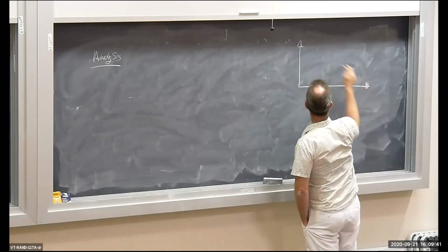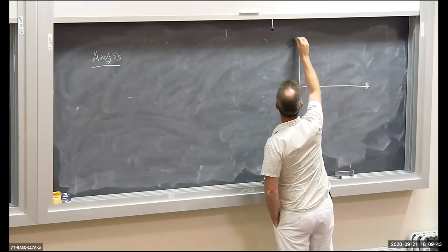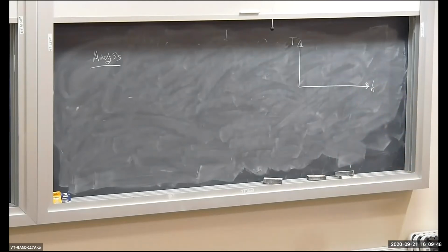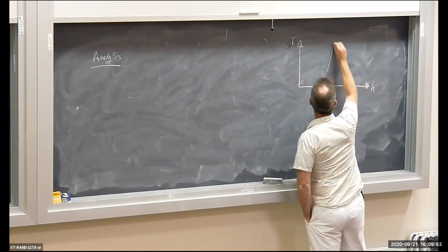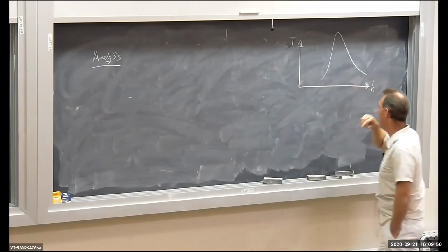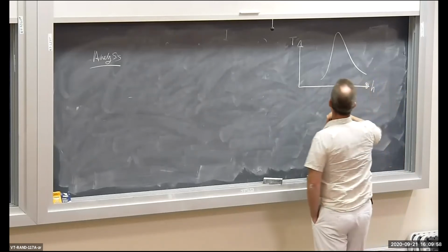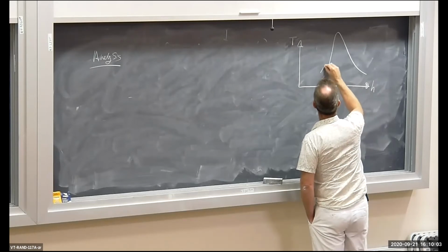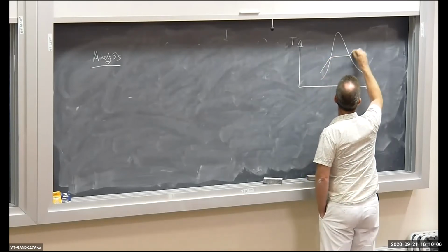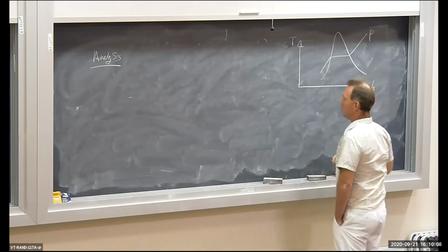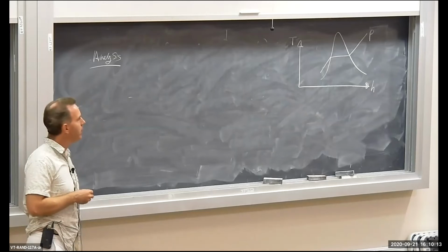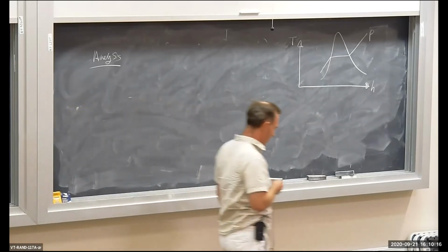Instead of putting temperature and specific volume here, I'm going to do temperature and specific enthalpy. It qualitatively looks the same as temperature versus specific volume, so we're going to have the saturation dome. So here's our saturation dome right here, and here are our isobars. Okay, so there's an isobar right there. So T-h instead of T-v, just so we can figure out what's going on.